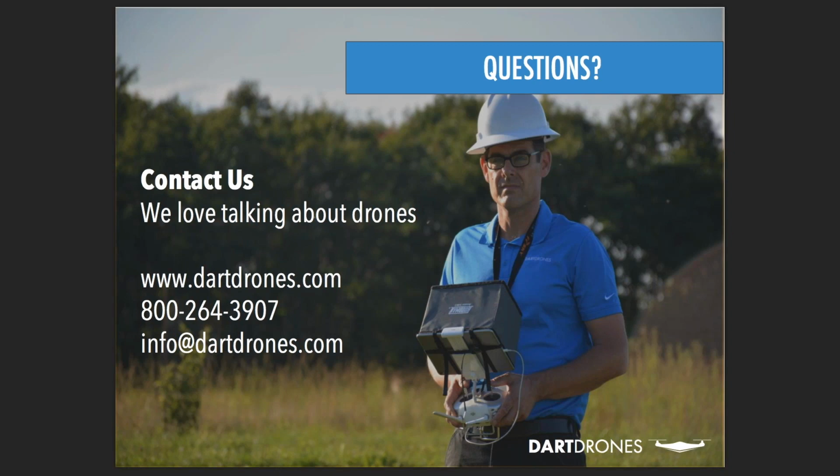The one thing I would just add to that really quickly is that when you're doing the flight planning in DroneDeploy, on desktop or on mobile, you can just see for yourself. When you draw out your area, we'll show you an estimate that's fairly accurate of how long the flight's going to take, how many images you're going to capture, and how many batteries you're going to need. If you're not connected to a drone, those are all based off the Phantom 4 Pro. But when you plug the app into your controller and the drone's connected, those estimates are recalculated based on the actual drone that you're using. So you can just go check ahead of time.